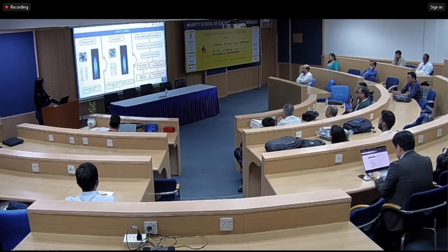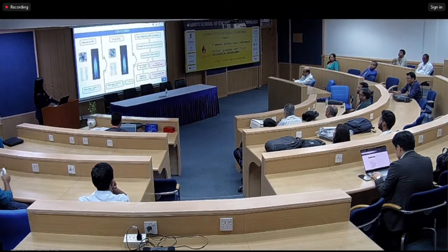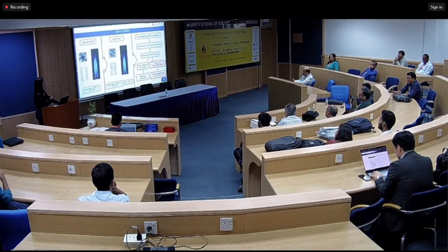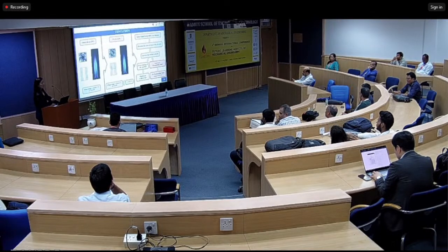So this is the conclusion for our study. As I have said, we compared the reference smooth burner at 4 kilowatts and S8 at 3.2 kilowatts, so that we obtain the first ignition flame. The comparison is about the design. You see this is the black body in the middle of the air slot, right? And we also obtain a stable flame, and the flame temperature is improved by around 3.5%.